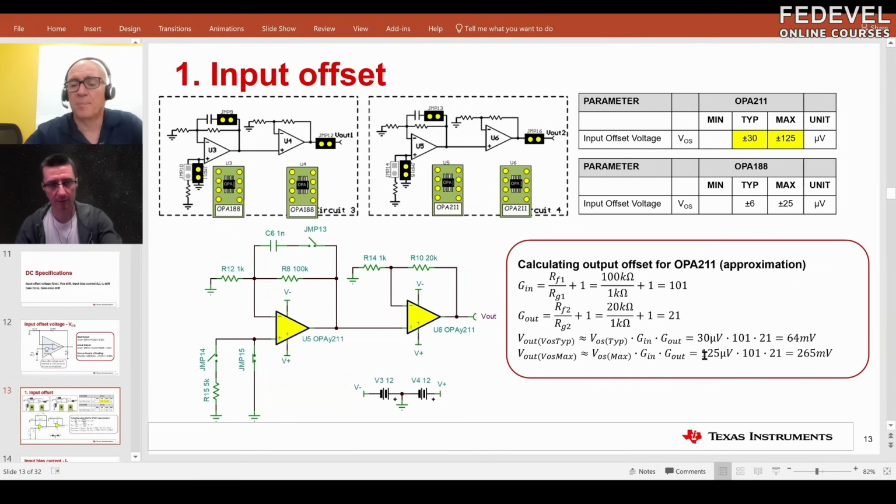So these are numbers from the datasheet, or these are measured numbers? Datasheet. These tables are just how it would be displayed in the data sheet. Microvolts of offset on the input doesn't sound like much, but when you look at the output signal, it can be hundreds of millivolts or even higher. And this is actually a very low offset device.